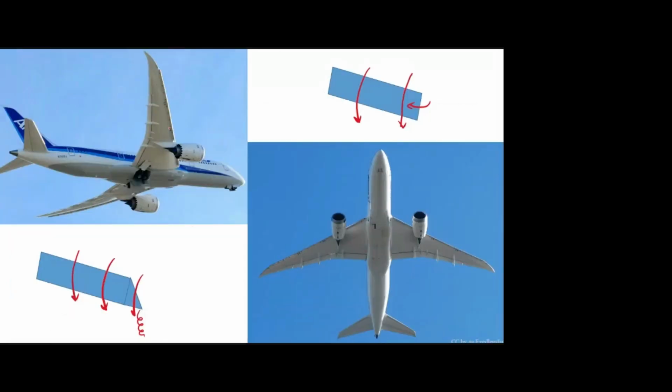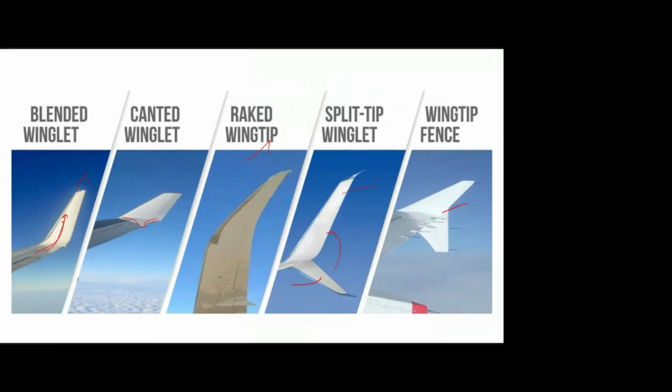Now we will come to that raked winglet. If you take the normal wing, what will happen? There is a free stream flow and there is a side leakage. So this produces a big wingtip vortex. But if you use this raked winglet, that means we are attaching another portion, like a triangular portion here. Here also there will be a free stream flow on this small triangular portion, and the wingtip vortex is formed only on this small sharp corner.